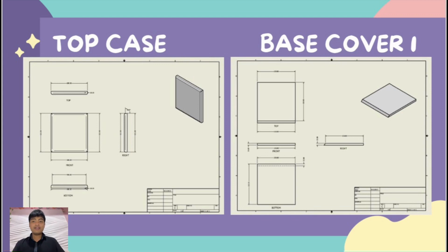So from the bottom view, the base is equivalent to 560 millimeters, with the base from the top being 600 millimeters. So the side of the chamfer for right and left is equivalent to 20 millimeters. That being added is equal to 40 millimeters, subtract that from the 600 millimeters, and you will get the base value for the bottom view. Now moving on to the base of the machine.